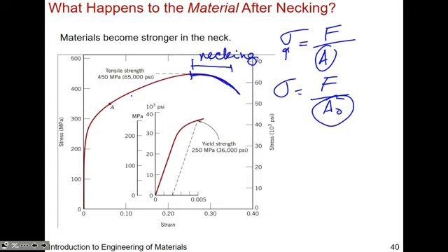So in reality, if you're plotting a true stress curve, you'll actually see something that looks more like so, and you probably have come across it, something that looks like this, if it's the true stress, because now you've normalized by the new A, okay? Yeah, so you may or may not have seen it if you're working in a lab that makes these kind of measurements.